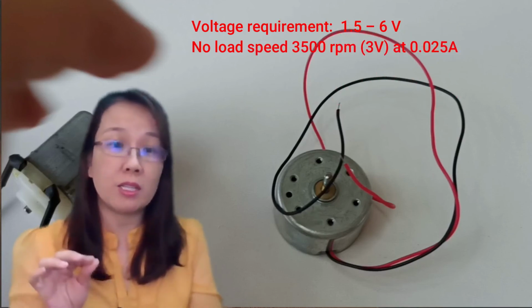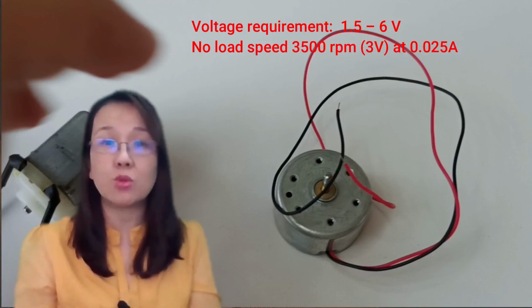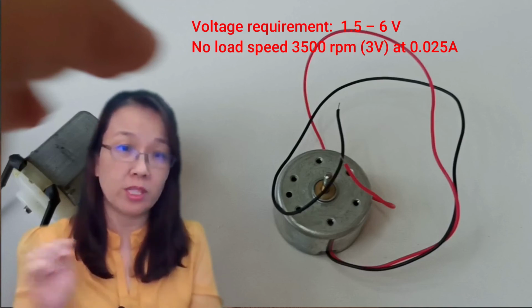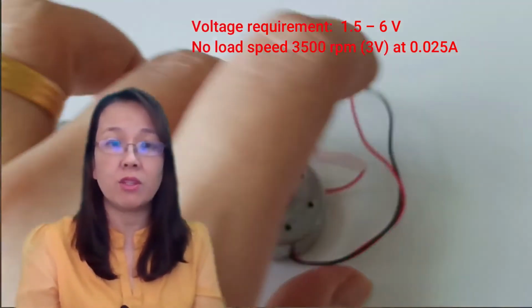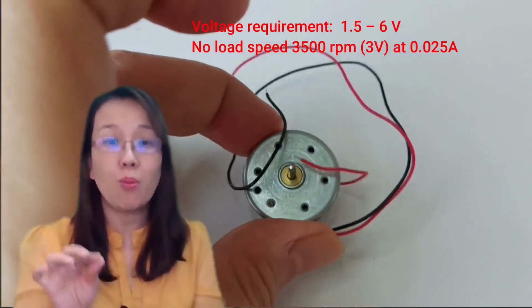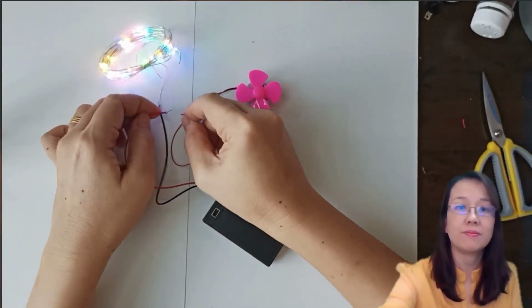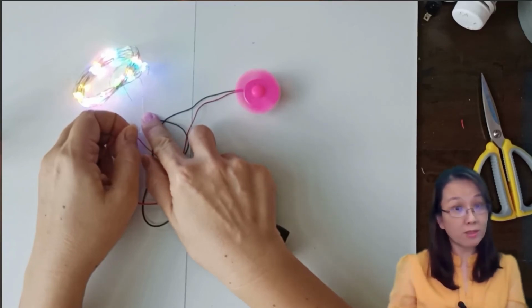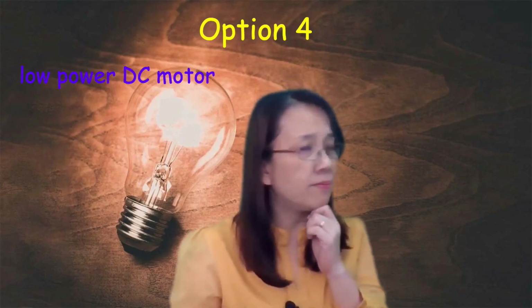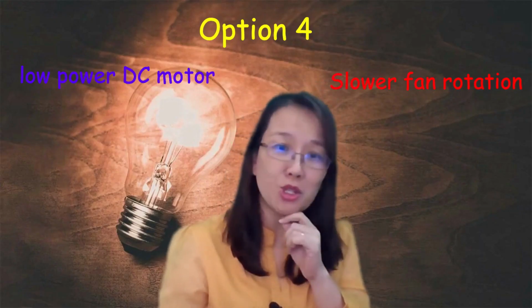So it only requires 1.5 to 6 volts of voltage, and it has a no load speed of 3,500 RPM at 0.025 ampere. This motor seems to require less voltage and current. Let us try this motor in a parallel manner with the fairy light. Well, it worked. However, the rotation of the fan seems to be slower.